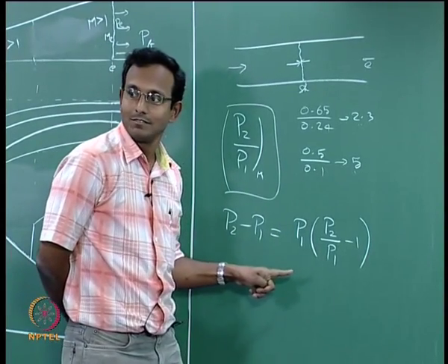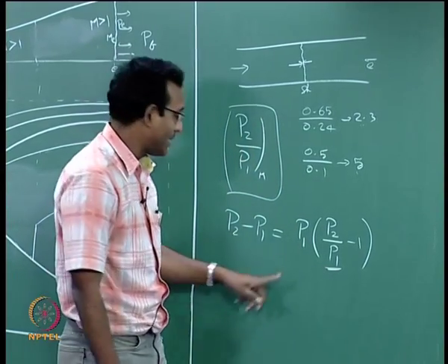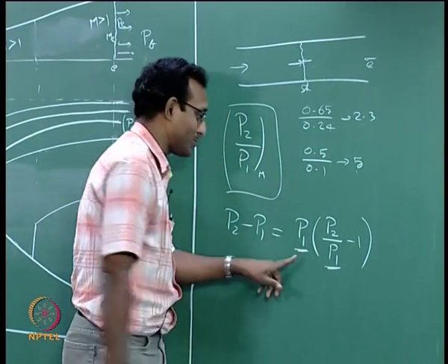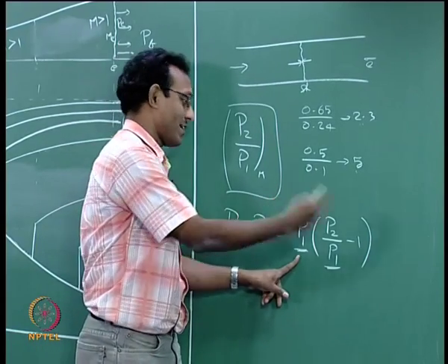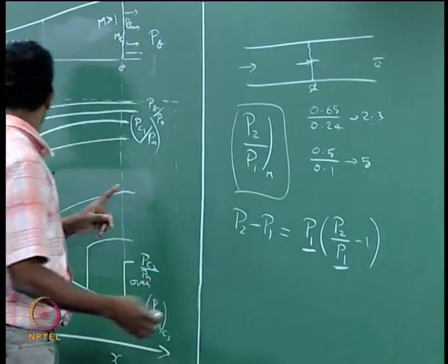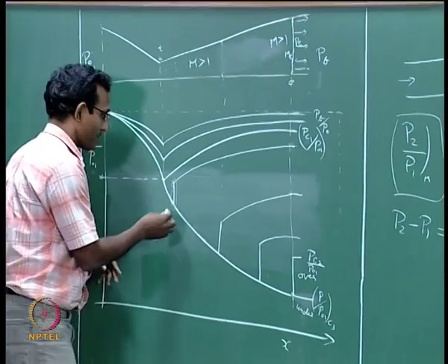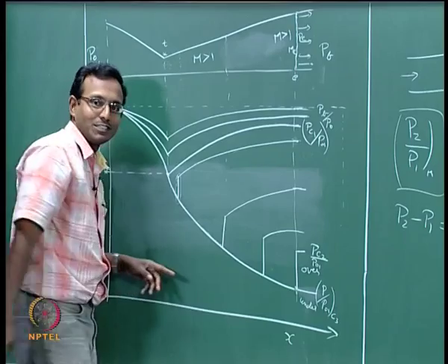This is what it is. Okay. It so happens that this number increases, but I am multiplying by a very small number. P1 keeps on decreasing with Mach number increasing, because the shock goes to higher and higher Mach number. The pressure on the supersonic curve, we will go to this plot, I can even go to the screen, but this is better. When I go along this supersonic solution, my pressure keeps on decreasing.